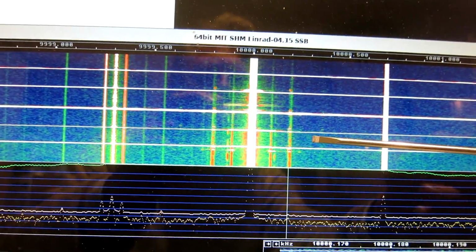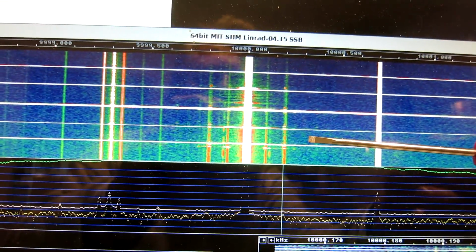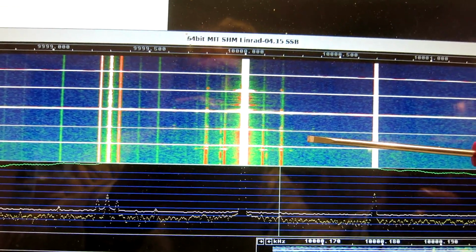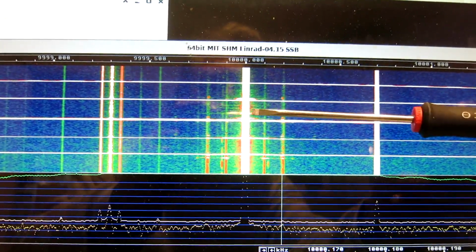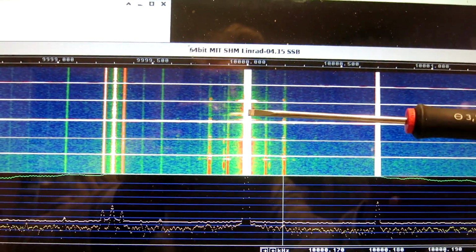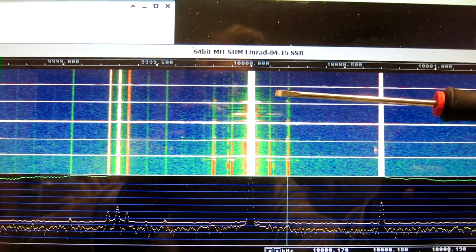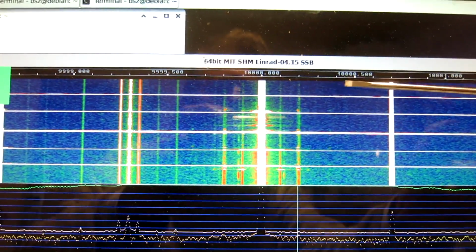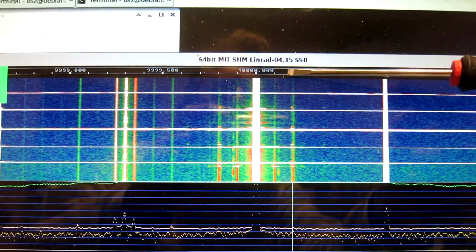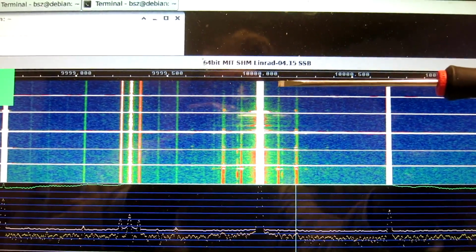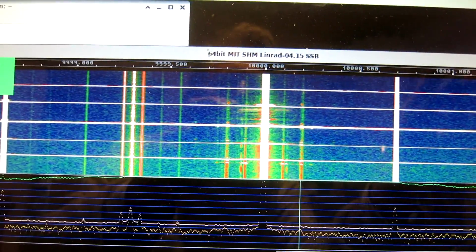And here is 3 dB more attenuation, and we can still see an elevated noise floor. So 6, 9, 12 dB. At this point there are some odd phenomena close to the carrier. And then 15 dB, 18 dB. Here it looks pure, but the carrier is 18 dB weaker. So to make an oscillator, this is not very good.